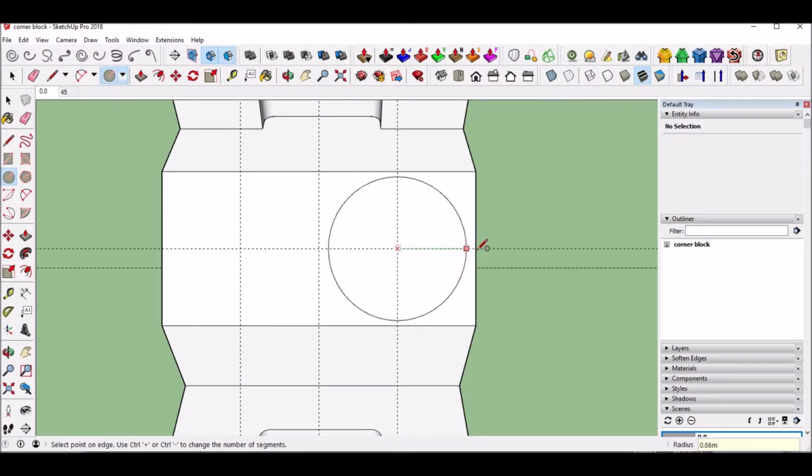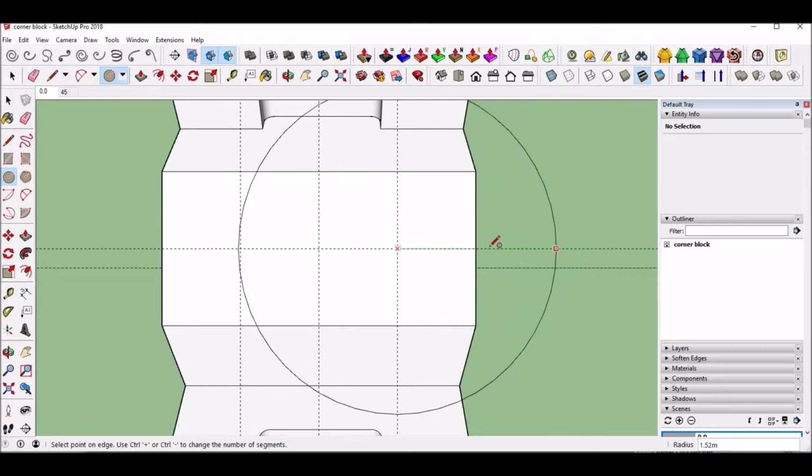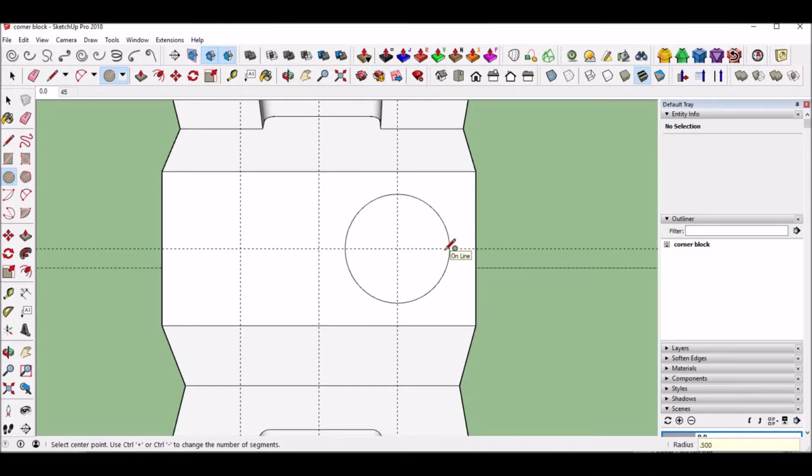Make it a little bit smoother of a circle. Okay, see now that's a lot smoother of a circle. And they're 0.5, they're 1/2 inch. That doesn't look right, because SketchUp does it in radius, not diameter. So we need to redo our thinking. That is 0.25. Okay, much better. Then if you click, not hold, but just click it and then drag to the right, it'll automatically stop at your last dimension. I'm just going to click it, and to verify, the bottom right corner says 0.25.